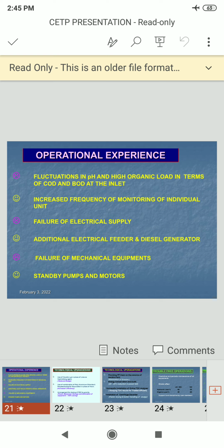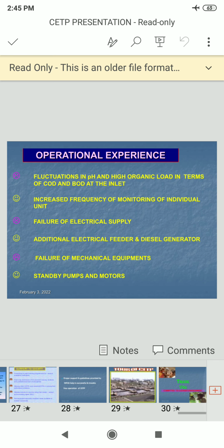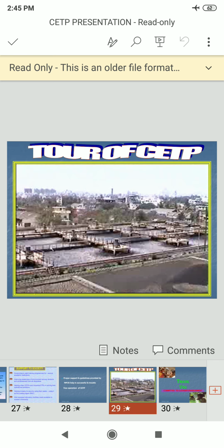The removal of biodegradable organics. Biodegradable organics, materials of plant or animal origin, are usually possible to treat using conventional wastewater treatment processes such as activated sludge or trickling filter. The activated sludge process is a biochemical process for treating sewage and industrial wastewater in the presence of oxygen, microorganisms, and biologically oxidized organic pollutants.